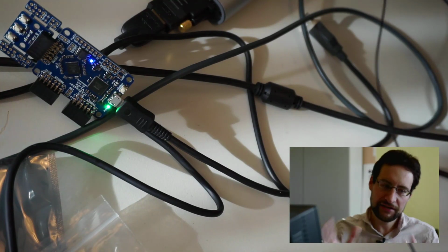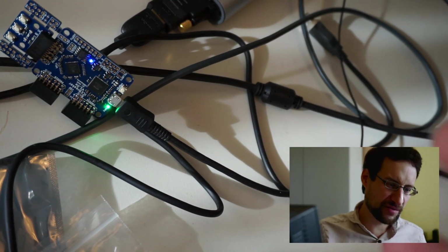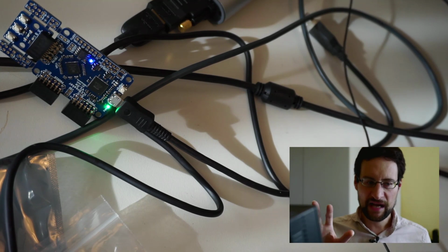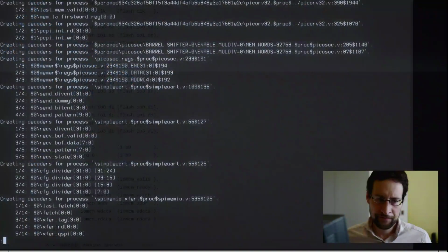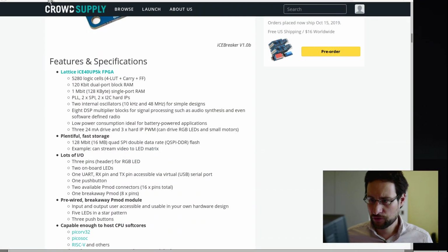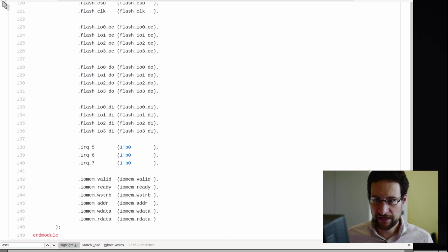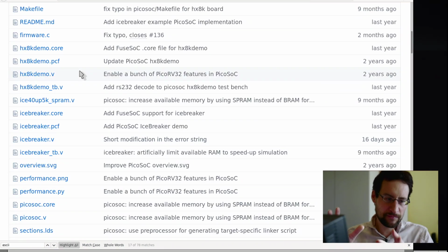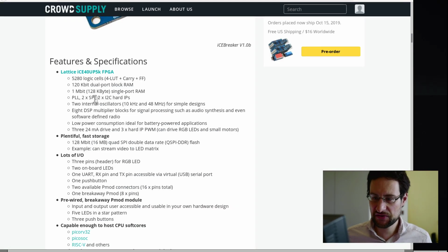That means taking this HDMI module and adding it to the Verilog here. This would look like adding a file here, in the simplest form just copying this HDMI output PMOD into this Verilog example, and changing the makefile to also build it along with the Pico RISC-V core. And then of course it doesn't work so easily, so this is a little bit challenging.